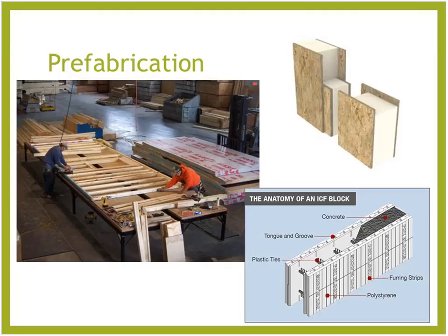And then these structurally insulated panels get set right out on site, and then concrete gets poured right in between them, as well. And a lot of these are used for resiliency. So people use ICFs for their bathrooms or for their entire house to guard against tornadoes or hurricanes, which gives the house a little bit more strength. They even make structurally insulated panels with concrete instead of the OSB to make a stronger home. So again, a lot of this reduced waste.